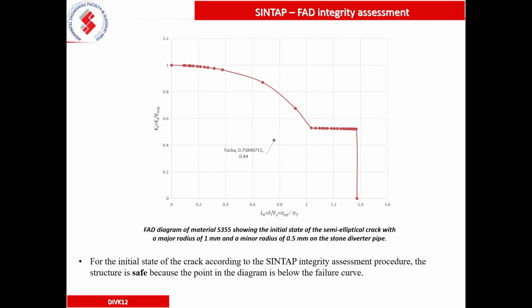So it's somewhere here. It is relatively close to the failure assessment diagram line. Maybe it is not so far from that line. It means that maybe a slightly bigger crack could be practically critical for such an approach, but still this initial crack is in the safe region.